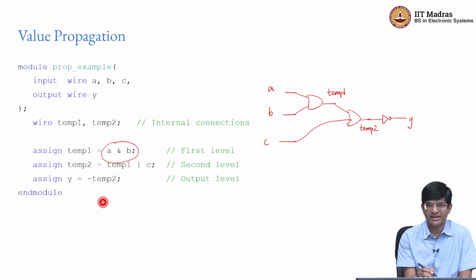So all of this is entirely possible. You could have it happening in any sequence, and the fact that these values propagate down these wires and finally come out at the output is essentially the entire model underlying how Verilog is simulated and what its functionality means. And this is the basic part that you need to understand as far as modeling something with Verilog is concerned. What exactly does it mean to write modules in a certain way, and how would it get evaluated as you go through?